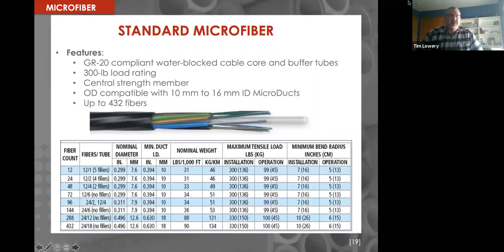There are string binders once you get up into the higher fiber counts. So you'll have your tubes, as you can see, the 12 and 1 and with the fillers, and then there will be string binders to differentiate your different bundles inside each tube. Go ahead.